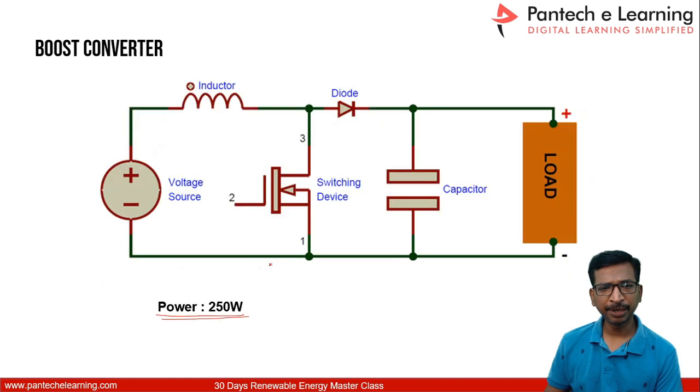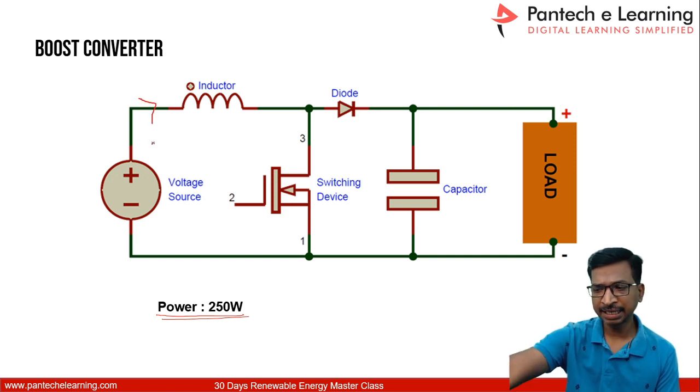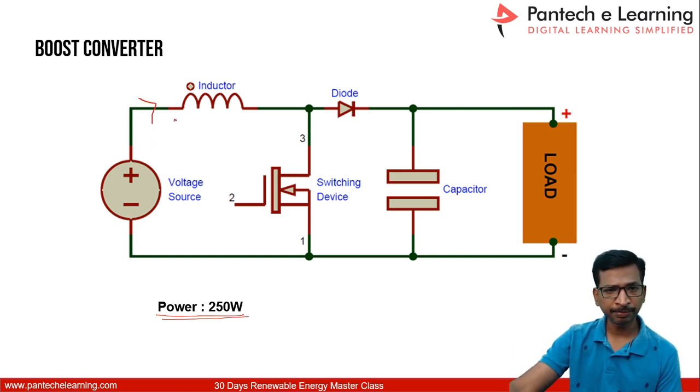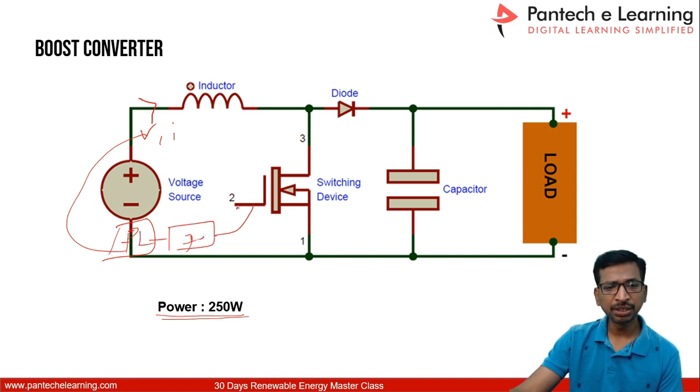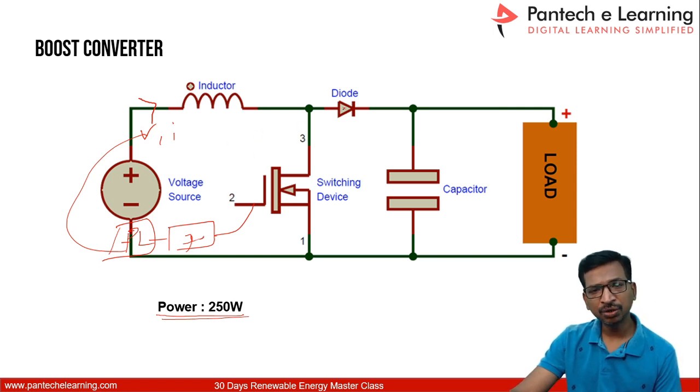Now if you apply this, then we have to add one DC-DC converter and PWM generator to activate that. See here, we have to measure the voltage and current from this block diagram and apply it to the fuzzy logic unit. This PWM converter is going to generate the PWM pulse to activate your boost converter.